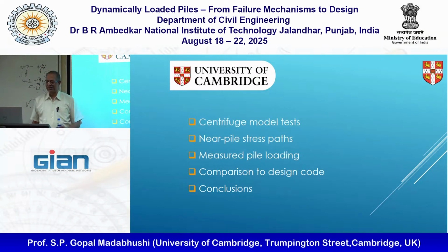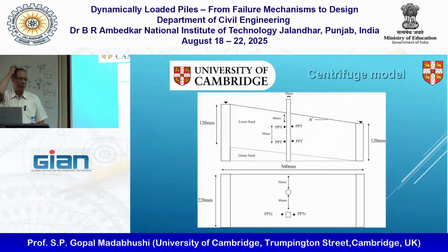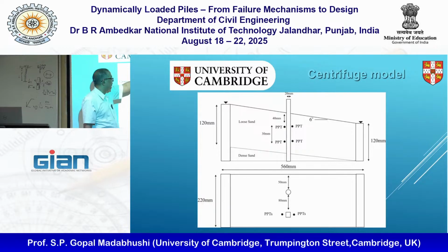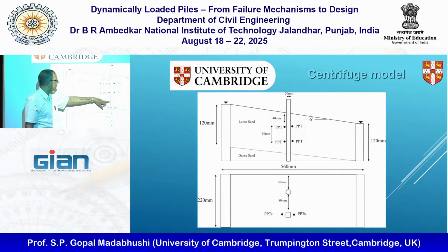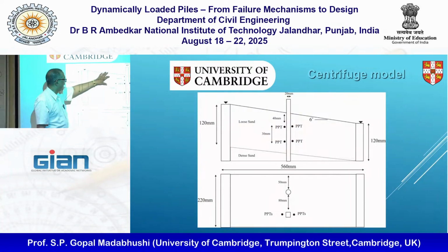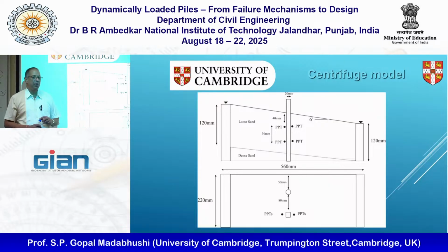And then I'll provide some conclusions on the single pile. So the experiment was dead simple. Just a single pile, no vertical load. The pile went all the way through the slope into dense sand. But if I look at this in plan view, we actually had two piles, one behind the other, because the width of the box is big enough.